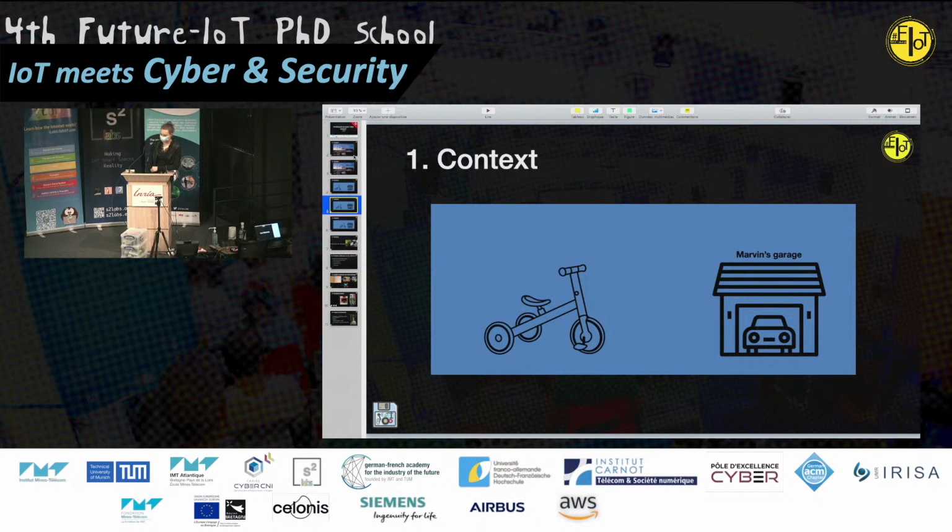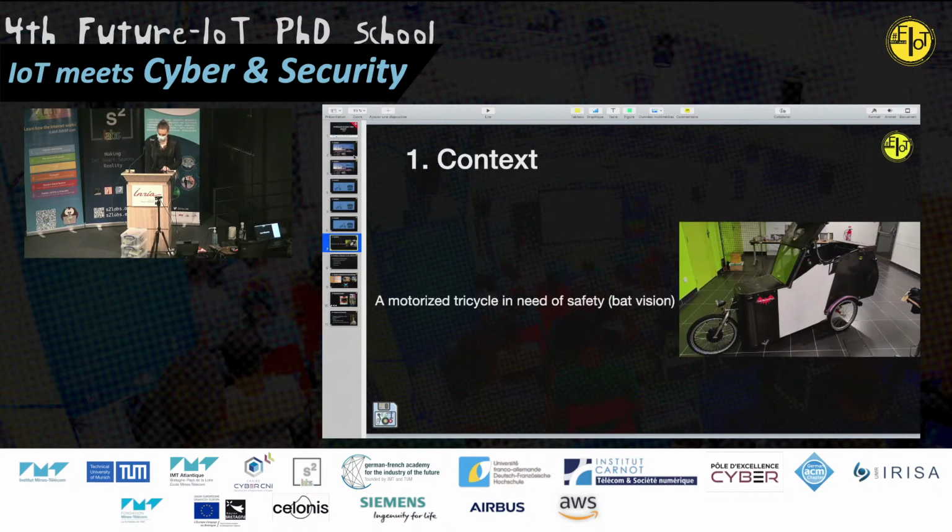Now that technically translates into providing it with a system that picks up danger related to front and back collision. The system will have to detect objects in the front and the back, pick up the current speed, compute the level of danger according to which it will display a warning.